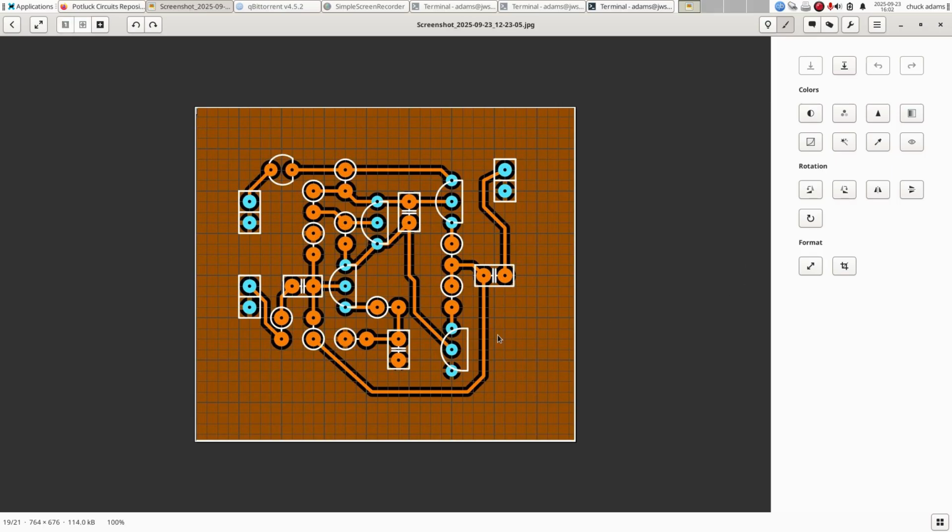Here's a board laid out, and I apologize, I did this for myself. I did this one by having the 1/8 watt resistors vertically mounted. Circle shows where the part is, and one end is stuck through the hole. Bend the wire, the top lead over, and insert in the adjacent pad.